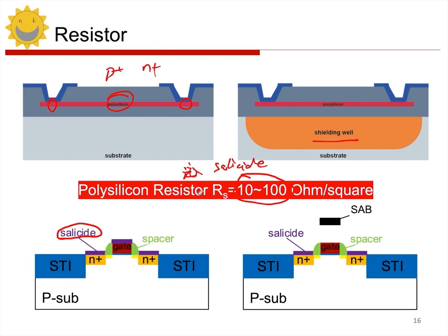Let's take a look at what this is. First of all, during the integrated circuit processing, the entire area is actually coated with this material, and then the positions that need electrical connections are left intact, while the rest is etched away. The active area, the region above, and the gate are covered with a purple layer. This layer reduces resistance. Connections to source and drain improve, thus parasitic resistance lowers.